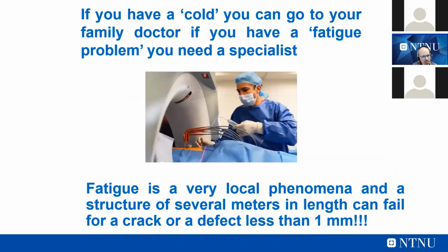So what I usually say to my students is that if you have a cold, you can go to your family doctor, but if you have a fatigue problem, you really need a specialist. So fatigue is a very local phenomenon, and a structure of several meters in length can fail because of a crack or a defect that is less than 1 millimeter. So we need to be very careful in how we manage fatigue problems, and this is also why there is still interest in these fatigue problems, because it's still a challenging topic to be faced.